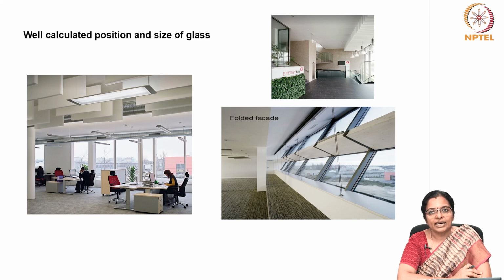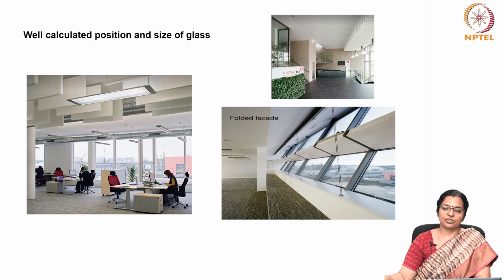The natural daylight in the energy base building in Vienna is another example of how energy can be conserved by tapping natural daylight. The glazing on the south facade is slightly overhanging to increase the proportion of diffuse to direct sunlight entering the room, while incorporating PV panels and reflective blinds enhances daylighting as well as taps the solar energy.